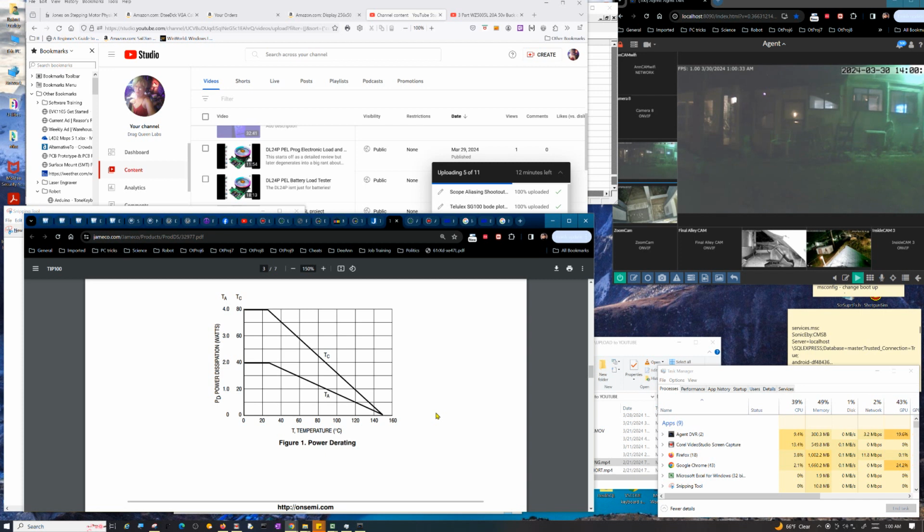Even in forced air, you may be making assumptions about where the actual cooling air is. Maybe that component is so far away from the cooling air stream that it might still be getting air from underneath, say on a vertically mounted circuit board with a transistor sticking out the side of it. You still may be getting most of your cooling air from the bottom, not the top, if it's too far out of the airstream.